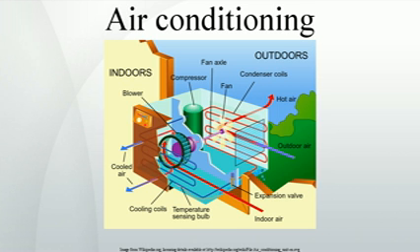Cylinder unloaders are a method of load control used mainly in commercial air conditioning systems. On a semi-hermetic, or open, compressor, the heads can be fitted with unloaders which remove a portion of the load from the compressor so that it can run better when full cooling is not needed. Unloaders can be electrical or mechanical.